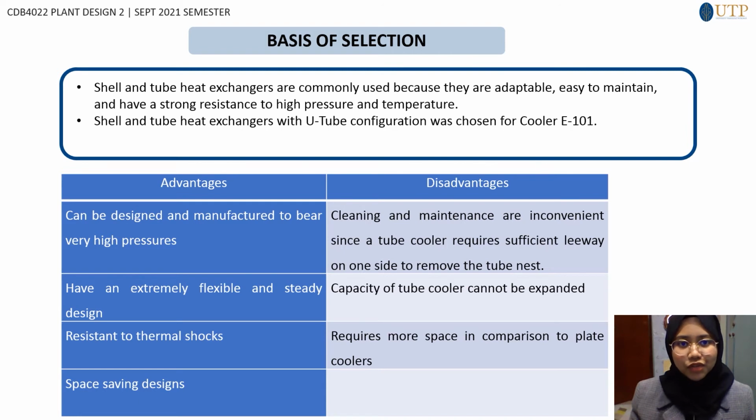Due to the bent individual tubes, a heat exchanger with U-tube bundles requires significantly less space than a straight tube heat exchanger with the same design. U-tube heat exchangers also only generate a low pressure loss during operation.